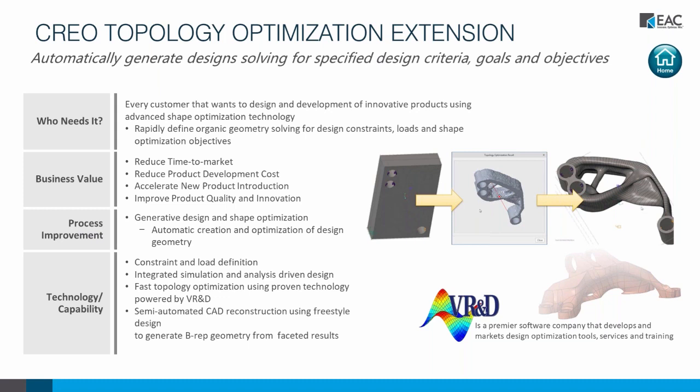What this particular product does is it's like taking a chisel or a Dremel tool to your part. It removes the material, again, taking into account structural considerations, so that this part has these type of forces acting on it, and it's held in this particular way. Remove as much material as you can and still have it be able to withstand those forces and the way that it's held and constrained within the rules that we set. So as you can see here, it takes basically this block part and hogs out a bunch of material. These are all non-parametric edits, right? It's just removing material. It puts a mesh on there and it just starts removing, and it ends up giving you something very similar to an STL file.